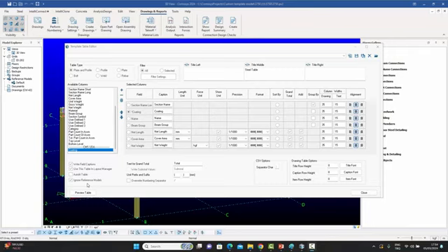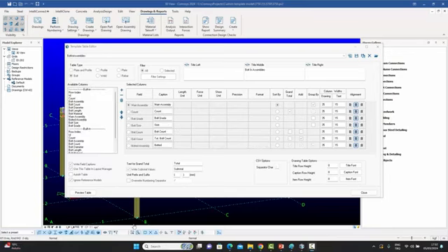You can choose to ignore reference models. So you might have your reference models appearing in the drawing as well, but you don't want the material list to show any material in the reference model. So you can select this, and it's like an automatic filter. You could have done it through the filter settings, but it's like an overriding filter you have over here. You have control over text, row heights, caption row heights and item row heights. All these font variables are available over here. So you have a very powerful system of creating more or less any kind of report which you want.